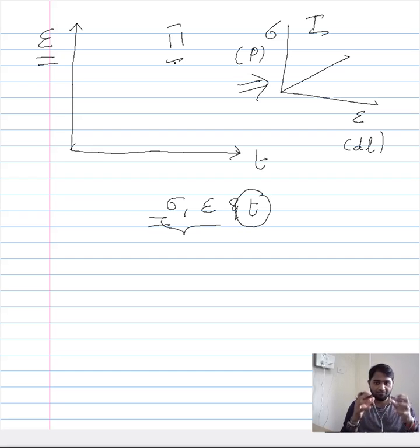If I have three varying interdependent components, stress, strain and time, then I need a three-dimensional frame of reference to plot the evolution. However, since we have assumed one to be constant, this allows us to plot the creep behavior in a two-dimensional plot involving strain and time. Since we have assumed that the mechanical condition we impose is constant, it is possible for us to plot the actual three-dimensional curve as a two-dimensional one involving strain and time.